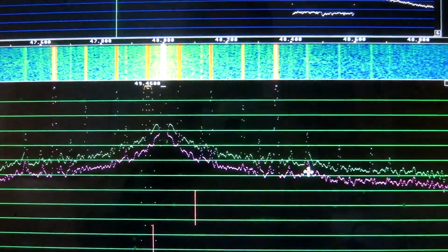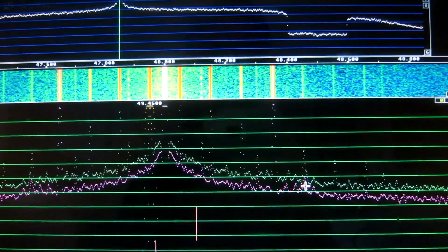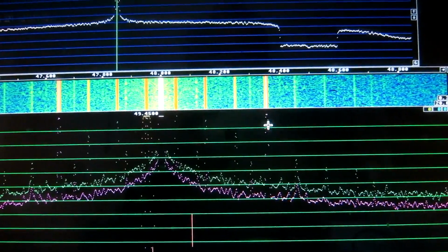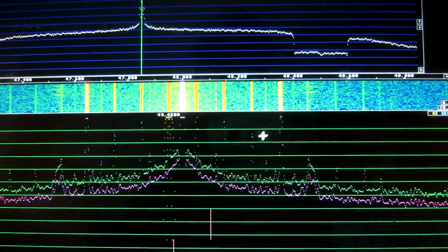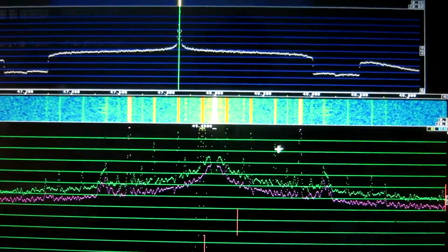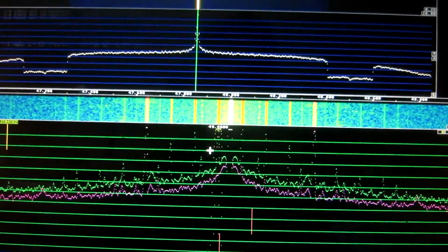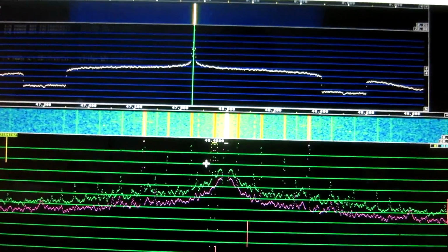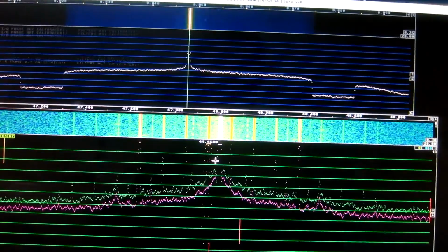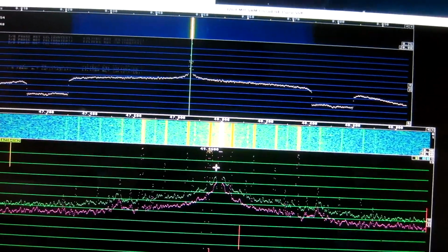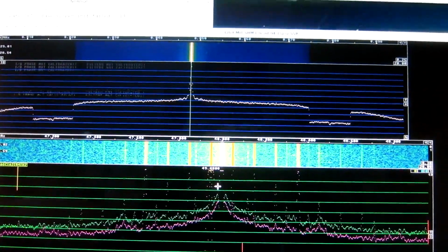No, maybe. Things are not fully stable. The signal generator is of course present both in the green and the red track here. So the big conclusion is there is a similar contribution from phase noise and amplitude noise at close range. So I go back to the perceives and try to establish the levels of the sideband noise